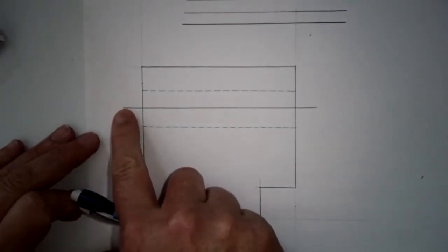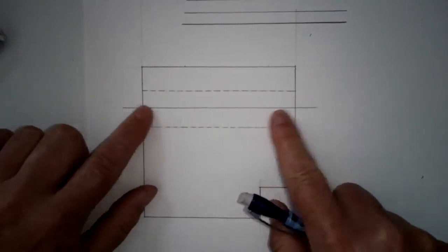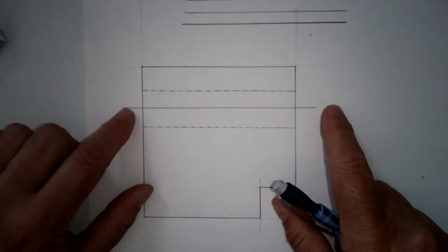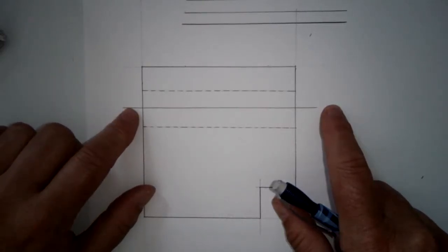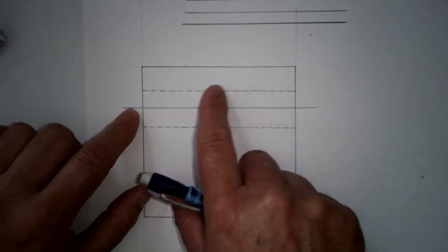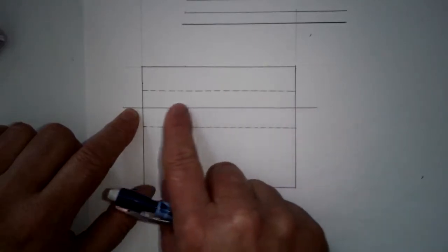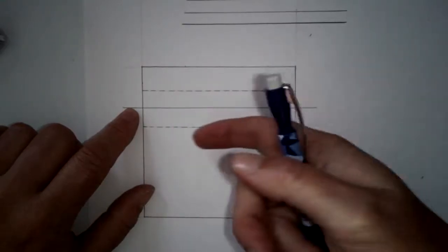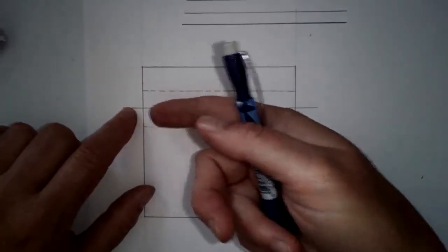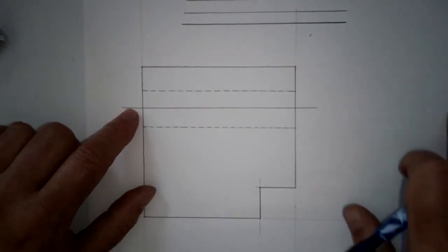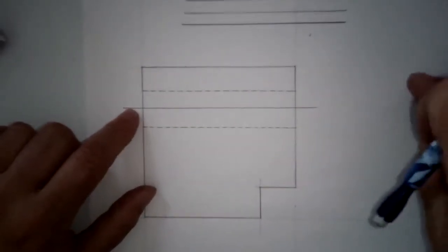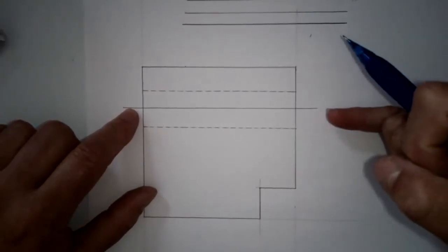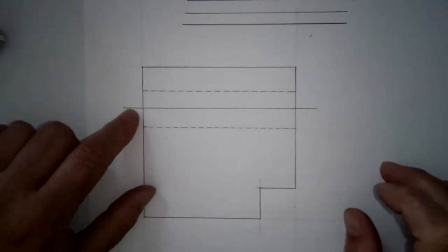The center, this is a center line, and it extends beyond the object lines because it's not representing a feature as much as it's representing a theoretical center of the feature itself. So this is representing the center of this hole. If it was being drilled in from this direction, we haven't looked at this view, so we can't see the true shape of the hole. But if we were to draw a view over here and show where that hole is, we'd see a circular feature of that hole, and then we'd see a center mark on it. This is representing that side view of that hole in the center mark.